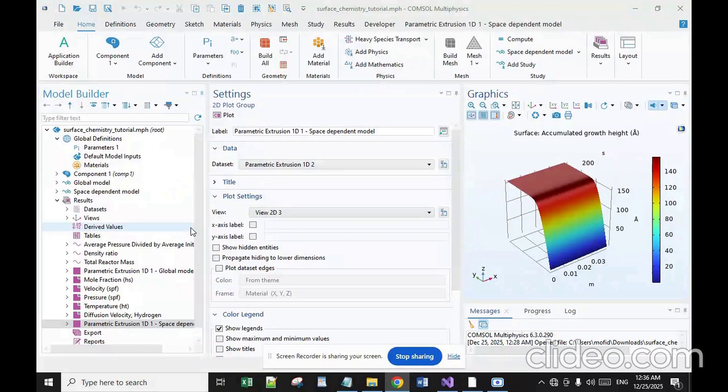The next one is ultra high vacuum CVD. CVD at very low pressure, typically below 10^-6 Pascal, or about 10^-8 torr. Note that in other fields, a lower division between high and ultra high vacuum is common, often around 10^-7 Pascal. And subatmospheric CVD, CVD at subatmospheric pressures, usually